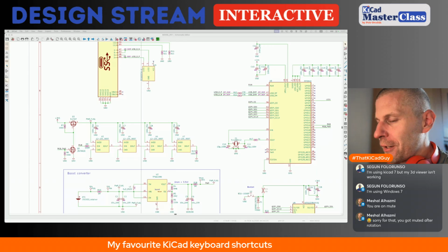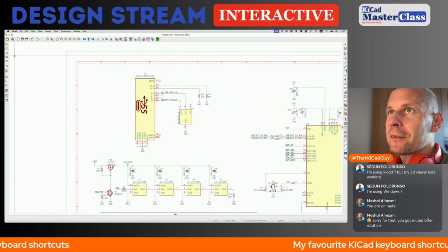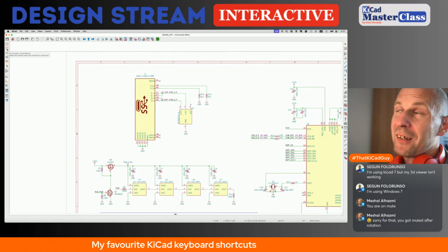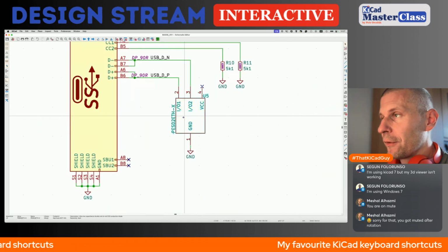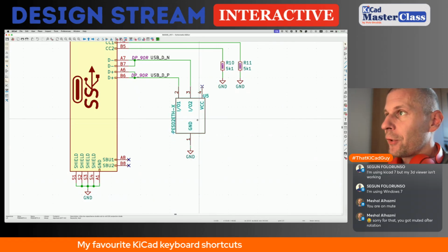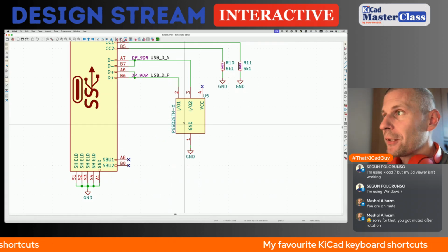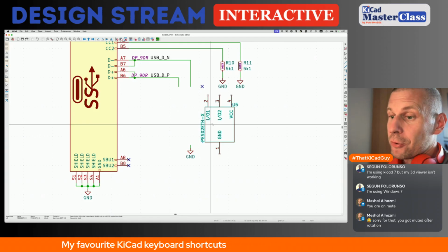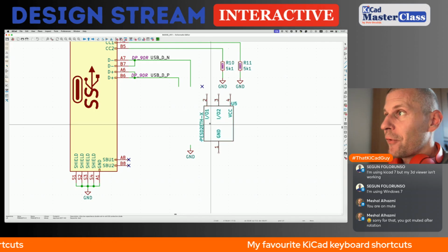So after rotation, I used the switch to fast grid, and I explained that I don't use it anymore because there is the new feature coming with KiCad 8, I think, grid overrides, where the symbols are placed in the standard 50 mil grid, but the labels, when the feature is enabled, on a much finer grid. When you are moving your symbol and pressing Command on Mac, or probably Control on Linux or Windows, you can then place it anywhere off grid.